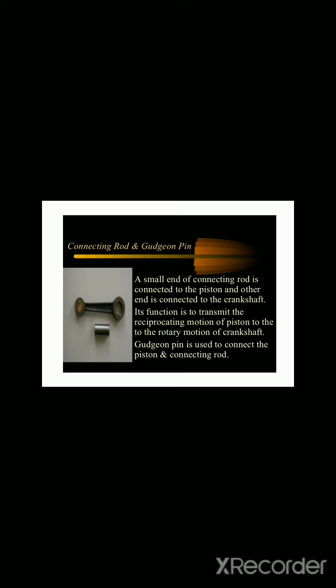Connecting rod and gudgeon pin. A small end of connecting rod is connected to the piston and the other end is connected to the crankshaft. Its function is to transmit the reciprocating motion of piston to the rotary motion of crankshaft. Gudgeon pin is used to connect the piston and connecting rod.